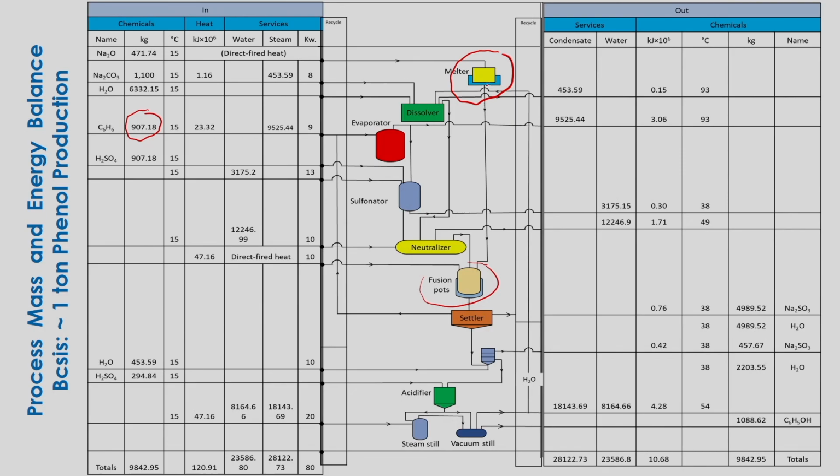And you will see that we have also done the energy balance, and accordingly the heat required for each individual unit is given here in the heat column. You will see different amounts for different compounds, and different for each unit. Also the enthalpy at the outlet composition is given, the inlet temperature of each component and the outlet temperature are given according to the calculation, and the outlet amount of individual compounds coming out from each unit are all calculated.